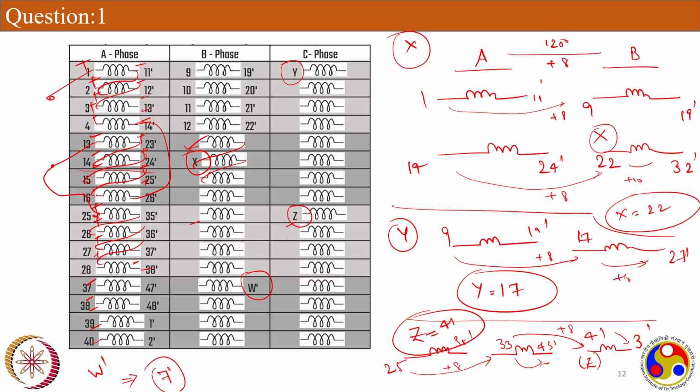So in this case, the maximum will be 16 V. You are saying maximum resultant voltages. Yes, you have 16 coils per phase. See the magnitude anyhow. If it is the same, then definitely it's 16 times the individual coil voltage. That's right. Multiply by the distribution factor. Yes, that's there because it's short pitched. For the maximum current,